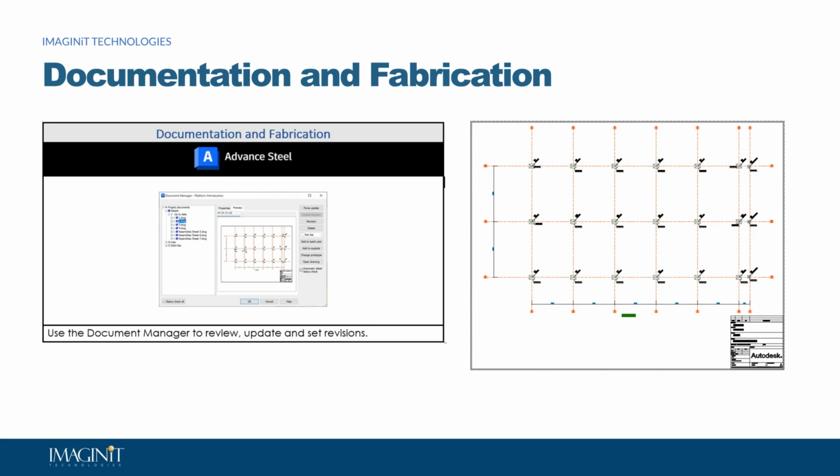Okay, so through here, when utilizing documentation in Advanced Steel, you're going to see this document manager. Basically, it's making drawings on my drive or on my server where my main project is, and setting up a series of folders for me automatically. And then I can find those quickly inside of the document manager in Advanced Steel. Open them up, tweak them out, I'm ready to go. And can do automatic revision updates and all kinds of cool things in here.